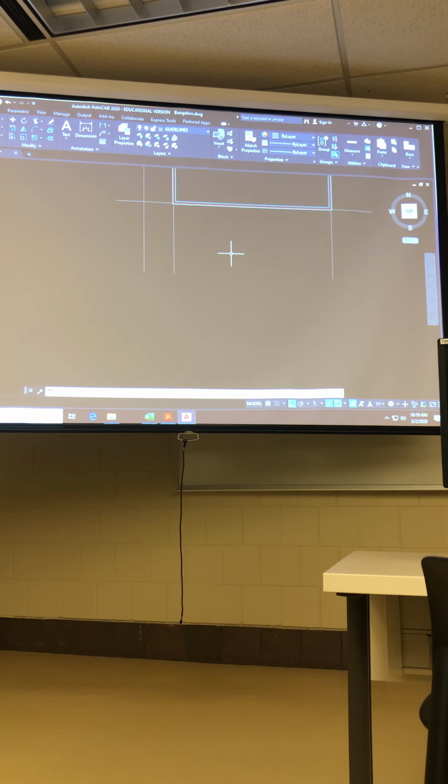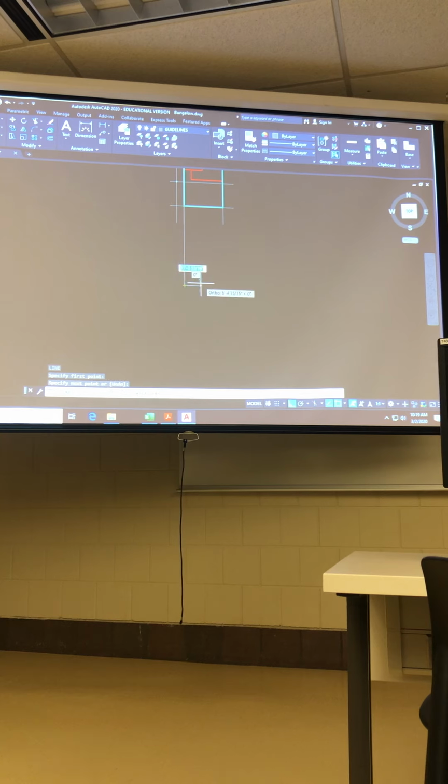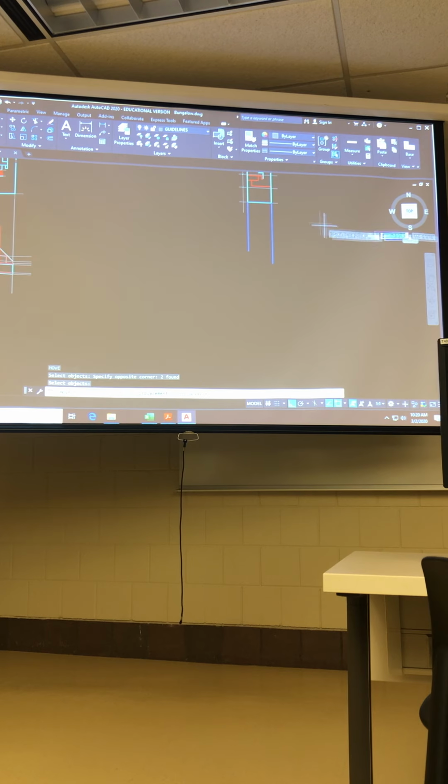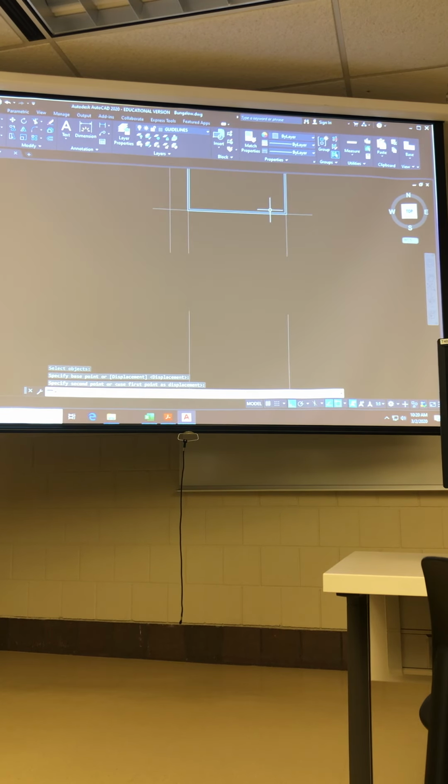What I'm gonna do is just zoom out a little bit. And I'm gonna draw my first guideline from the guideline where my exterior wall was in the plan drawing. From this corner, I'm going to draw that guideline down. And from this corner, I'm going to draw that guideline down. And I'm just gonna move them so that I can see them separately from the floor plan drawing above, okay? So why measure when you've already drawn the floor plan accurately, and we can just essentially use that as our template, as our background for the vertical guidelines here.